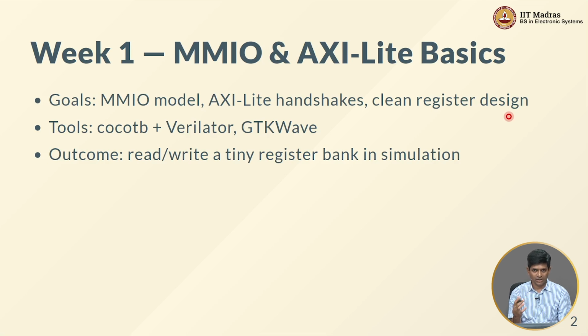Now, a lot of that will involve a sort of Verilog simulation demonstration, walking through how the Verilog code works and then actually looking at how we can simulate it. And part of that is I will be introducing a new tool for simulation which is called Cocotb. Cocotb is a Python interface which allows us to write a test bench in Python and interface it with modules that have been written in Verilog.